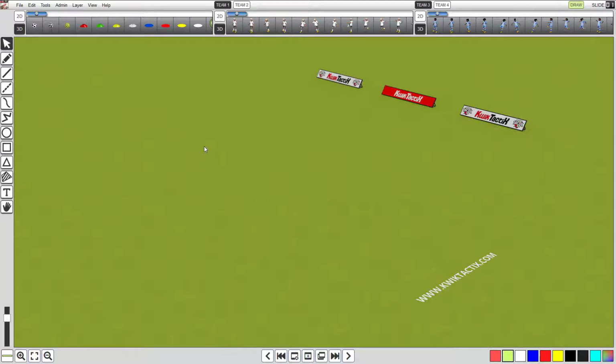Now let's drop a few markers onto the canvas and create some lines. You have 3 slightly different ways to drop markers onto the canvas. They all have the same desired result, but are slightly different in operation. The first way is to simply click a marker to highlight it, then click anywhere on the canvas where you want the marker to go. The marker will be placed, and the tool will automatically change to the selector tool, so you can immediately click the placed marker to show its available functions and modify if needed. Another way to add a marker to the canvas, and probably the fastest way, is to simply drag the marker from the marker menu and drop it directly onto the canvas, which achieves exactly the same result, without the hassle of having to select the marker on the menu.